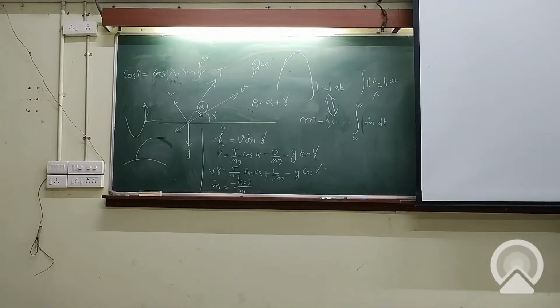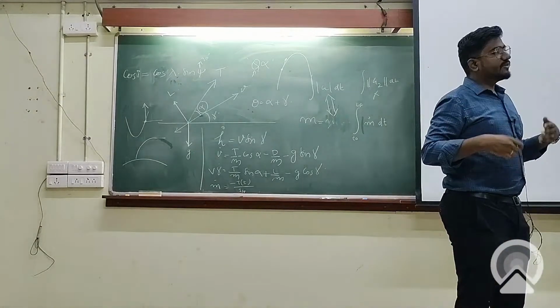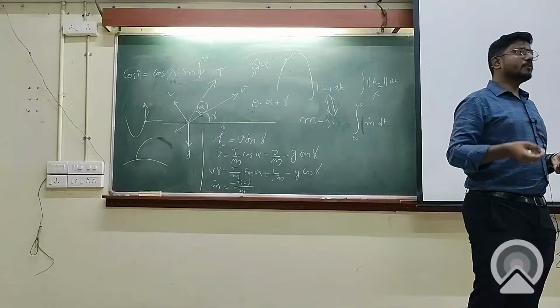Then you ignite the ongoing stage, but thrust is not sufficiently developed. What will happen? There can be a recontact. So you cannot separate the stage at that point. You have to separate the stage only at a point when the thrust has settled. That is one. Another reason for coasting is you want favorable ignition conditions for the ongoing stage. You cannot ignite the stage wherever you want. It has to be a favorable condition.